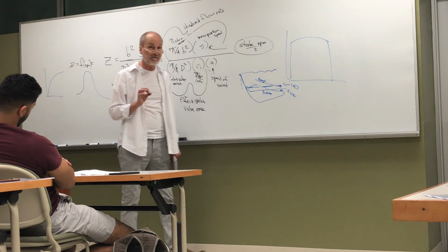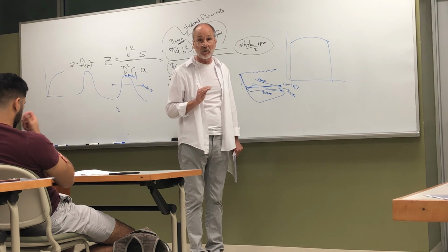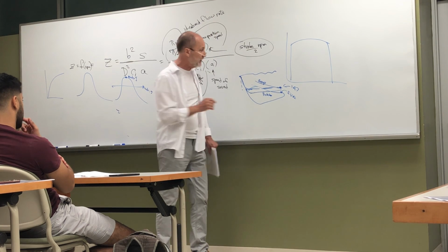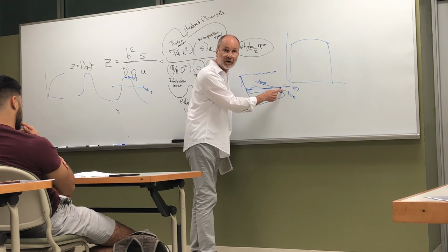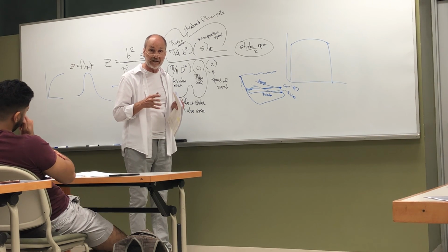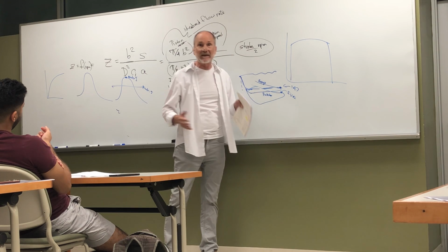Now at Mach index 0.4, we can still recover back to fundamentally atmospheric pressure, so we're not going to suffer a loss in volumetric efficiency. By Mach index 0.6, we don't quite make it back there. So we don't have as much fuel and air in the cylinder at Mach index 0.6 as we do at Mach index 0.4. And by the time we get to 0.8, we have a lot less.